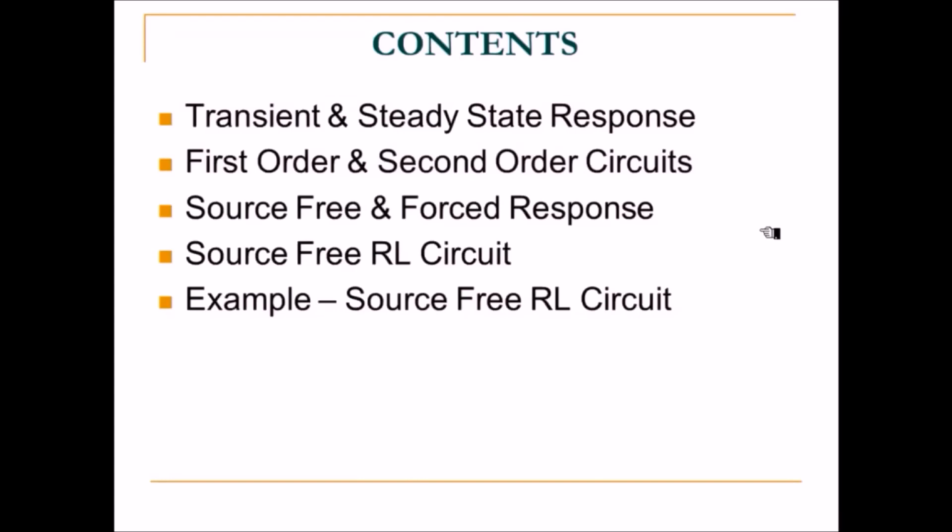So by that we are going to differentiate the terms transient analysis and steady state analysis, followed by first order and second order circuits with respect to DC transient analysis, then source free and forced response. Then we are going to consider one simple case of source-free RL circuit, followed by one example problem to understand source-free RL circuits.